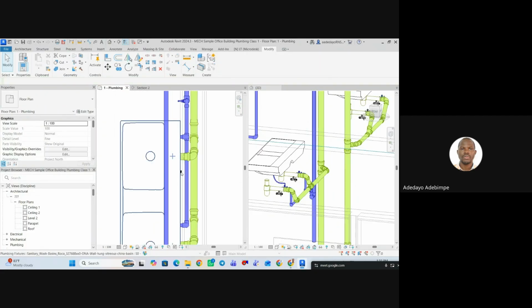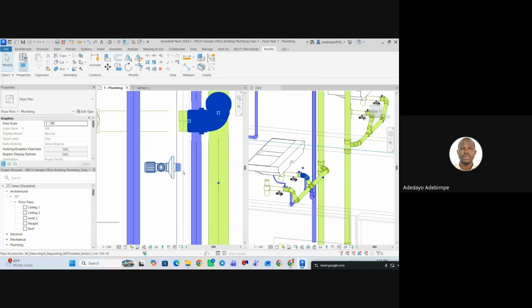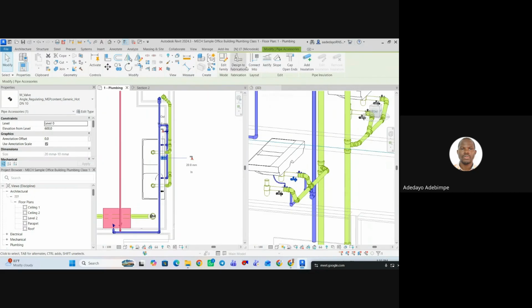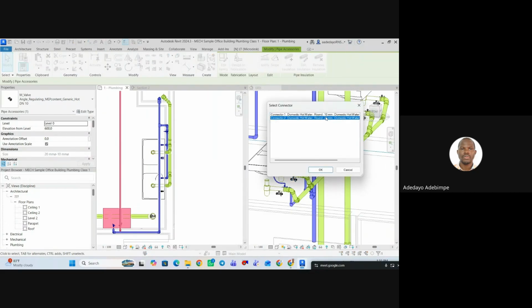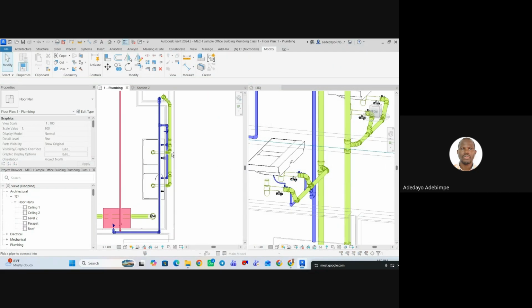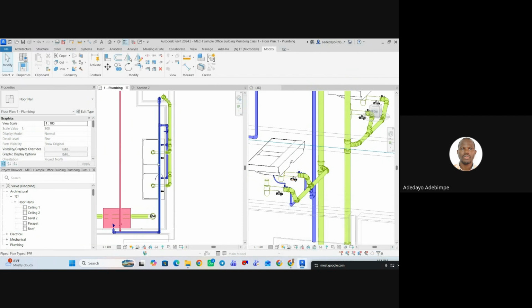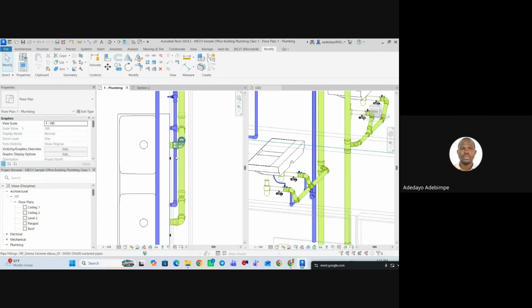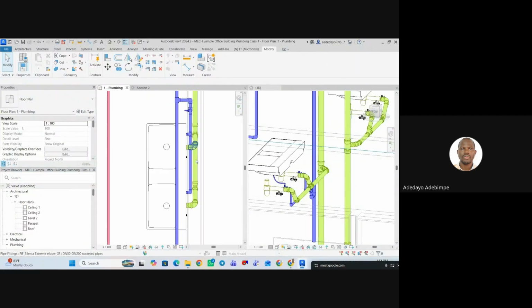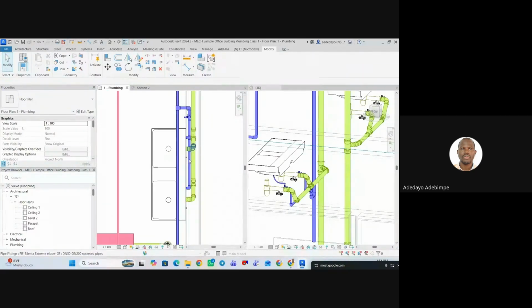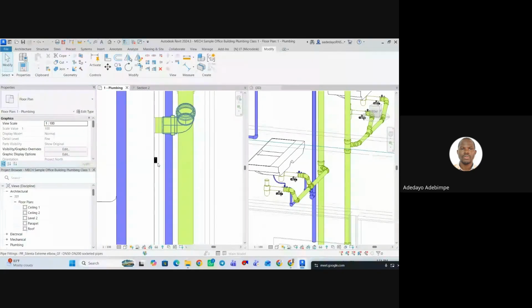Okay, I can pick this guy and I'll say connect into, pick the right connector. Okay, and so it's telling me no auto route can be found. Now, what's the reason for this? Probably at some point it couldn't pick a space. There's not enough space between the angle valve and the elbow it wants to place there. So let's just route our connections manually.